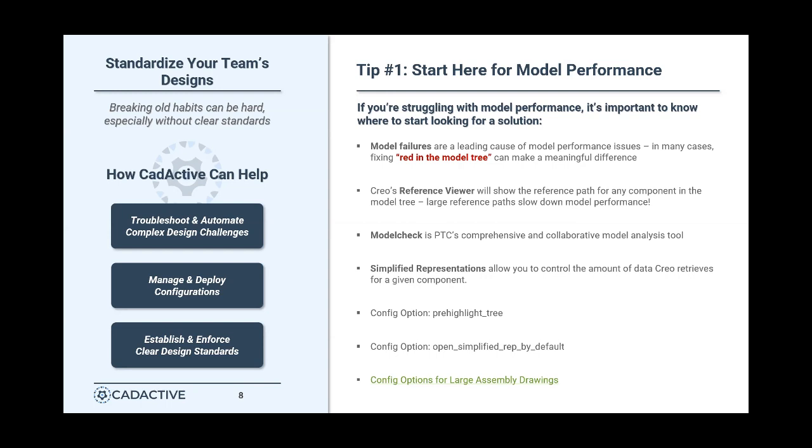And then as you click on different components, Creo is going to dynamically load those parts or assemblies into session. So that's another great way to improve your model performance because it allows you to only fully load into session what you are actively needing to work on.